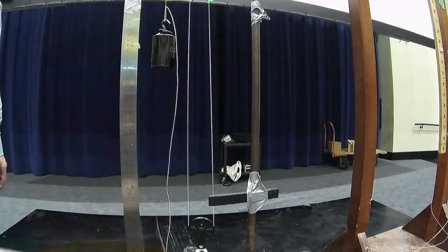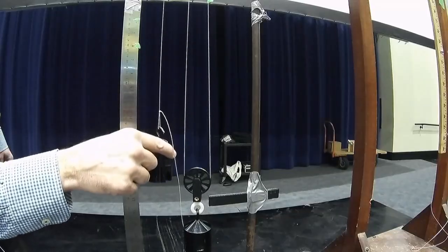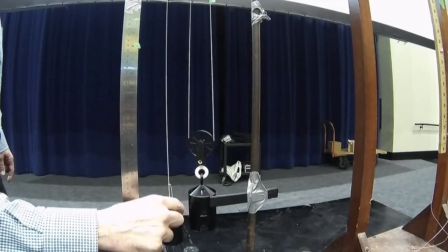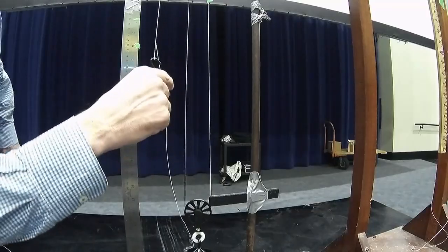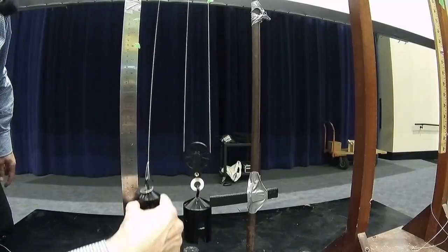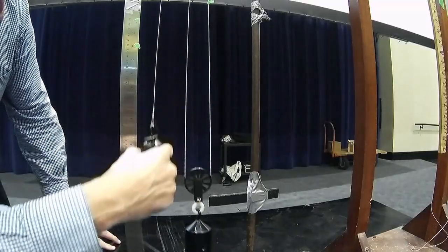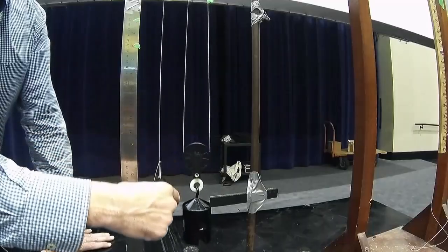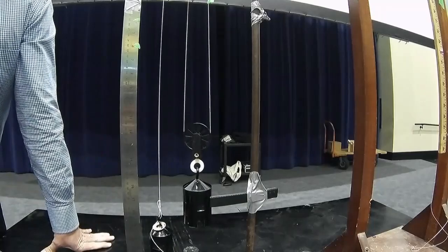What you've got is a 1 kilogram mass hanging down here and a half a kilogram mass hanging up here. And as I pull this one down some distance, you can see they're actually almost in equilibrium, even though they're completely different masses by a factor of 2. But I pull this down some distance, from 7 up to 17. So there's like 10 inches, but it only goes up 5 inches on that side. So the distance output is half as much, but I'm able to lift it with half as much force. So by using a complicated arrangement of pulleys, you can really increase your mechanical advantage.